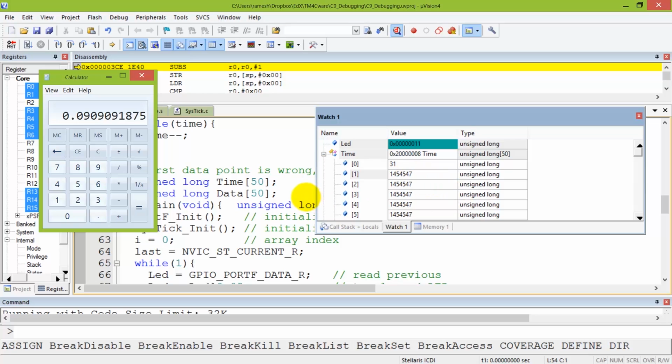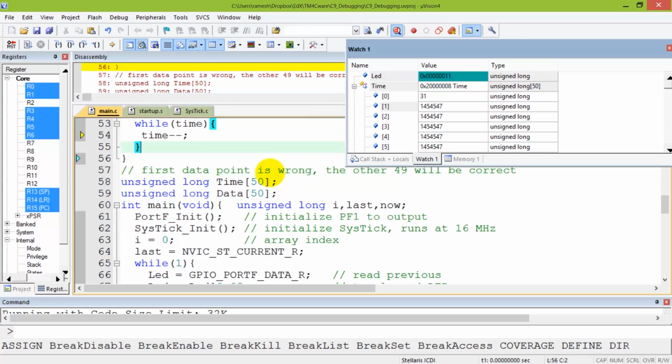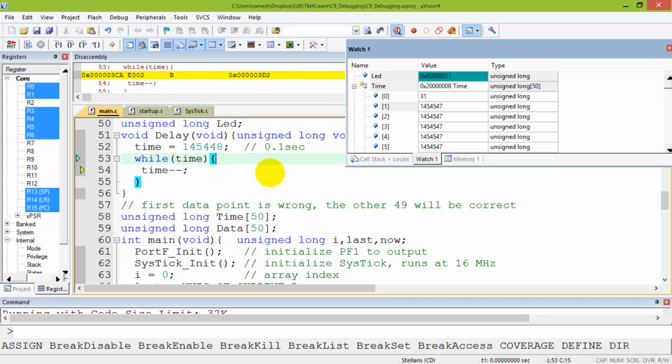Well, we can figure that out, because what happens is on the board, the time to do this loop where we decrement takes less time on the board compared to the simulation. So maybe this number is wrong. So maybe I'll change this. What if I change this to something appropriate? Maybe I'll change this to 16160. So I'm going to comment that out, and I'm right now testing to see whether I can get a more accurate value. So I save that, I quit my debugger,